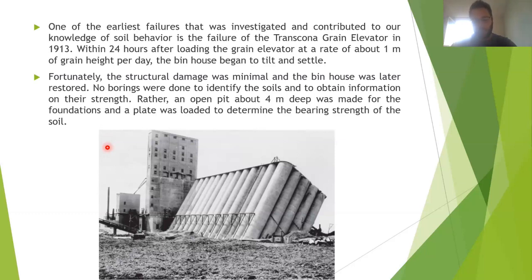So what you can do to prevent something like this from happening is to make good soil investigations. That's why I spoke about the norms we have in the European Union. You need to recheck what standards you have in your country, and see what the minimal requirements for investigations are. But the truth is, this is a relatively big building, so for sure you would have borings here.